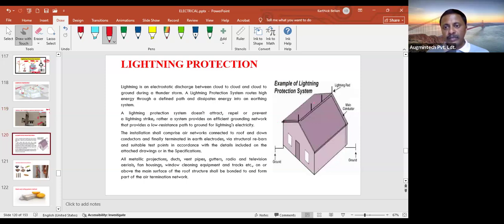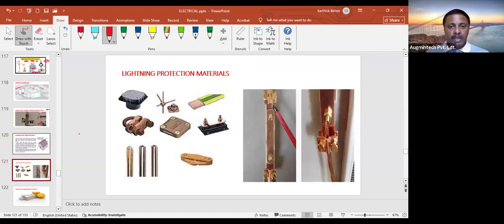So the same thing over here. These are the lightning rods, a down conductor, or we call it a main conductor, then connected to the ground. And you could see the supporting materials, this is the PVC down conductor. But in case of the roof, the open area, it is going to be a bare copper tape only. And then this is a lightning arrestor.